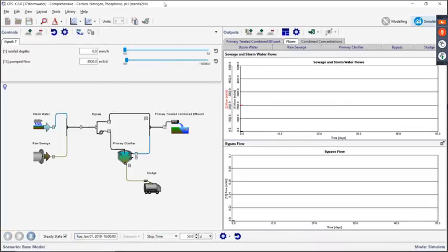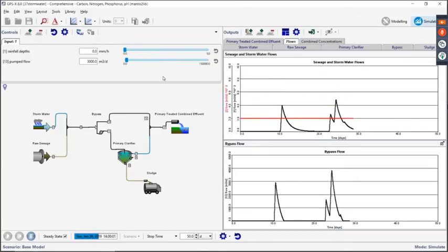If I go along here, we can see the flows coming into the plant, and if I go up and down like that to make a rainfall event, you can see it takes a while for the watershed to collect and deliver that flow to the plant. Eventually it goes back to zero, but I can make a bunch of weather happen one after another. You could theoretically have something generating weather for you, read it in from a file, or use a random number generator, whatever you like, and then the hydraulic delay of all that flow coming to the plant will be handled by the stormwater model. You can also characterize this influent. Right now, we characterize it as more or less clean water.